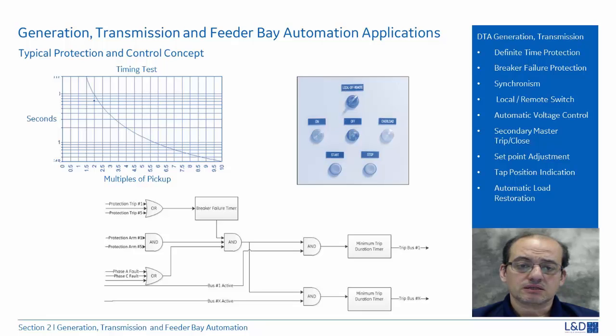Synchronism, that's basically synchronizing the voltage between 2 buses, and local remote switch setup. Normally we have a manual local remote switch, but you can also implement a software local remote switch, automatic voltage control, secondary master trip close, set point adjustment, tap position indication, and automatic load restoration.